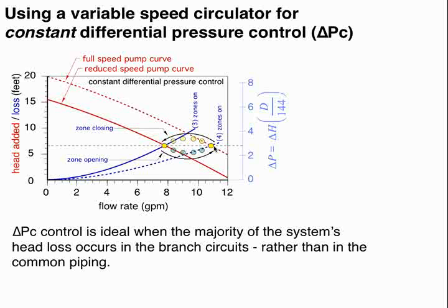But with the pumps that are on the market now, they have the ability to sense the differential pressure they're operating at and compare that to some set differential pressure. You've programmed in some type of a setting. Let's say it's 3 psi. Well, as this point starts to depart from that setting, the pump understands that. Just like the cruise control in your car understands when the car's deviating above or below the speed that you've set, and it immediately will change the speed of the motor to correct that situation. Okay, so you can think of this mode of operation in a pump as cruise control for differential pressure.